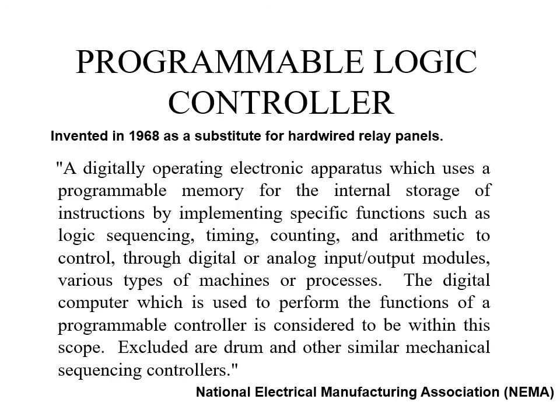Programmable logic controller was originally invented in 1968, and its main function is a substitute for hardwired relay panels. According to the National Electrical Manufacturers Association, or NEMA, PLCs are digitally operating electronic apparatus which use a programmable memory for the storage of instructions by implementing specific functions such as logic sequencing, timing, counting, and arithmetic to control, through digital or analog input and output modules, various types of machines or processes.